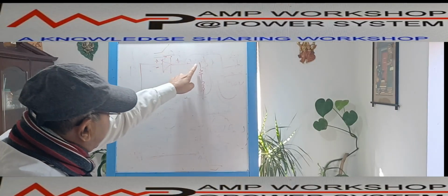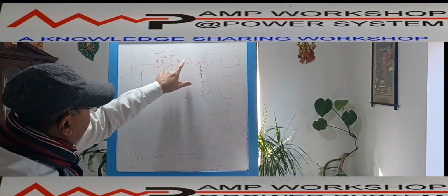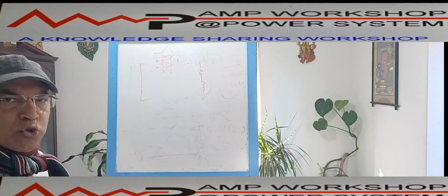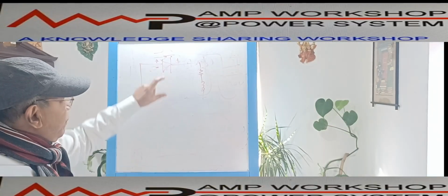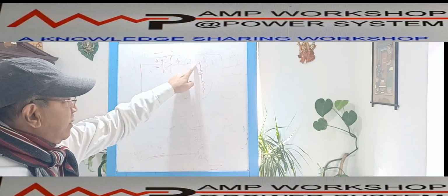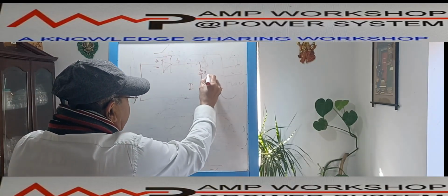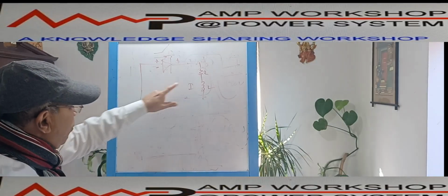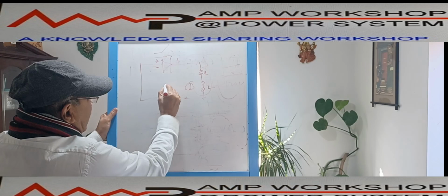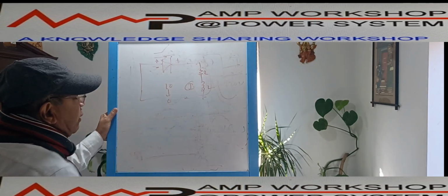But at that time, what is happening? This diode is a switch, but it's a high speed switch. Just before changing the switch, there is a current. So there is a current I flowing through this. This is a resistor, this is an inductor. The moment this current becomes 0, suppose the current is 10 amperes and suddenly the current becomes 0, then what will happen?